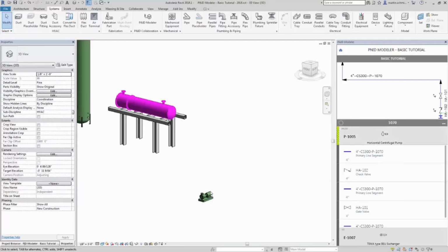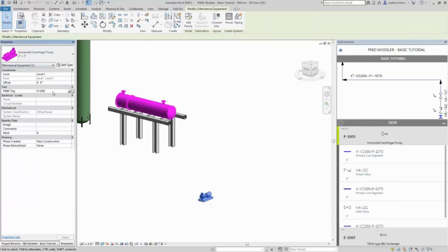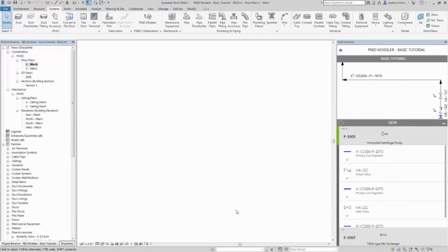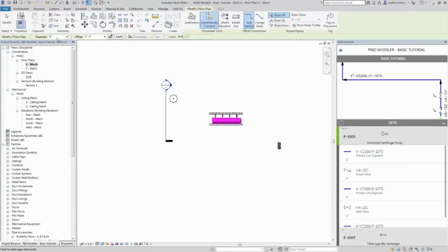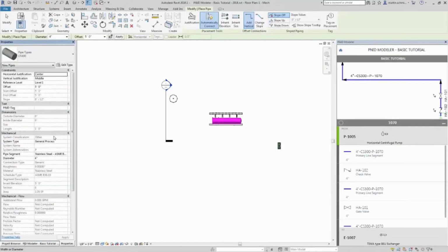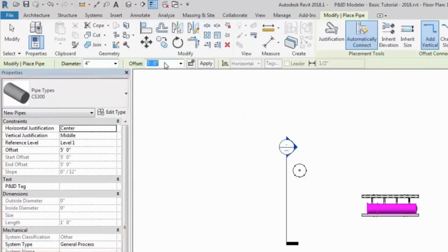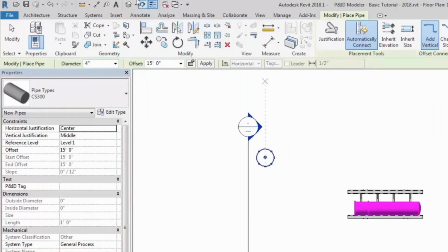Using this enables us to reuse that data in a Revit P&ID piping, so Revit piping model directly. Use it to simplify the creation of the model from the early stage schematic deliverables by minimizing manual entry. Because you're connected to the P&ID and the database, you don't have to keep entering things in, so you're removing that human error potential. You can also use the Revit tools to validate consistency between the 2D schematic done in Plant 3D and the 3D model. So if it changes in Plant 3D or if something's wrong in Revit, it will do a validation and can let you know.